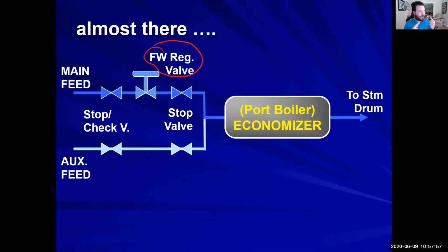You know certain conditions are going to result in certain things that will happen inside the boiler, which you will learn about when you go out on cruise, because these conditions happen a lot. These auxiliary feeds will give you that control, all right? Because you can't battle out a regulating valve and win. If it's sensing something, it's on its way. Remember, it's only got that one input. All right. So you can actually control your boiler water level using your auxiliary feed. And it's coming from the same pressure, the same source. And that's why one goes to both boilers.